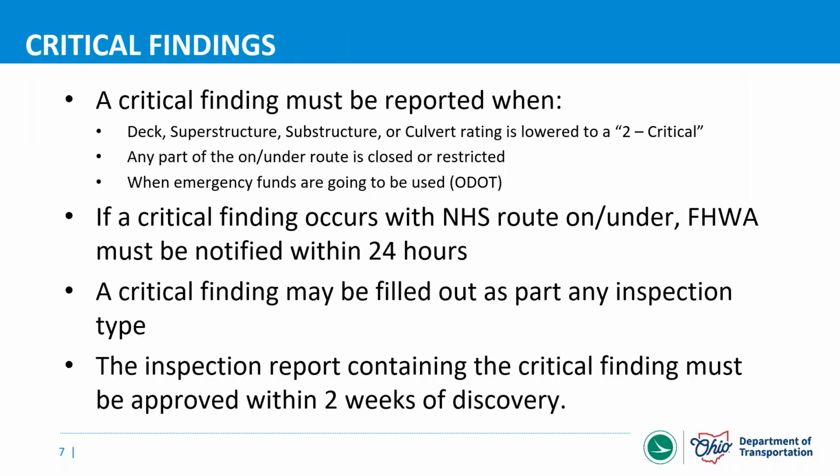The second bullet point is very, very important and a new change with the updated NBIS. If a critical finding occurs on an NHS route, so you have an NHS route on the bridge or under the bridge, Federal Highway must be notified within 24 hours. That is a little hard to do in certain cases, depending on the type of issue at the bridge.